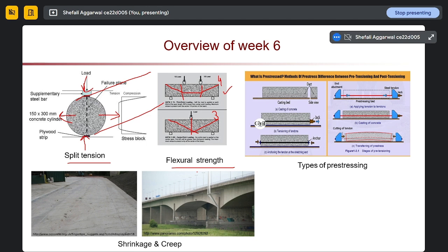That's why we are saying it should be, if you see this figure, a well graded system. We always say that our system should be a well graded system. In a well graded system, we have all types of aggregates from small sand to bigger aggregates, and they should be mixed properly, not separated out. So that is called the gradation of our aggregates.